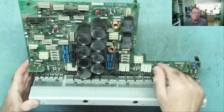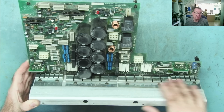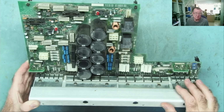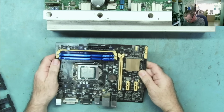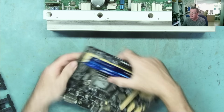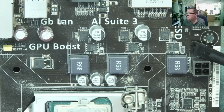And these are very common failure points. Quite often these will be mounted to heat sinks like we see in this case. Or again on here, the power devices are underneath this heatsink. But they may just be mounted to the PCB. So here is a motherboard, and these MOSFETs are power devices.